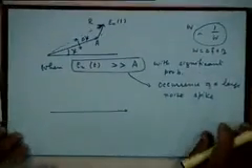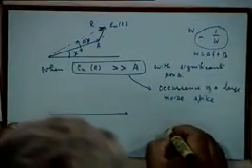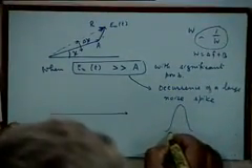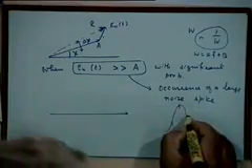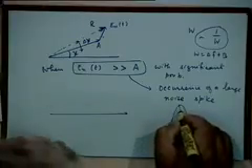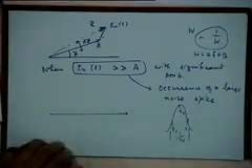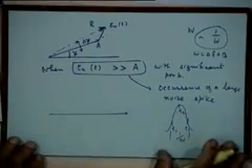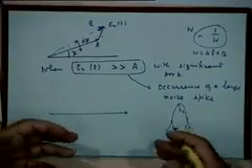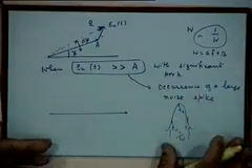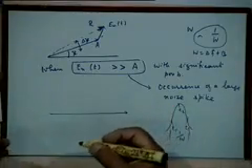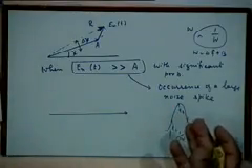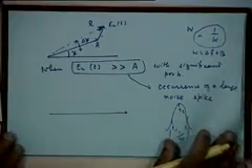Let's consider this noise spike occurs, and this duration is your 1 by W. Let me consider 2 or 3 instants within this spike, let's say T1, T2, T3, etc., where this amplitude is significantly large. So during this interval T1, T2, T3, the amplitude of noise is significantly large compared to A, much larger, right?